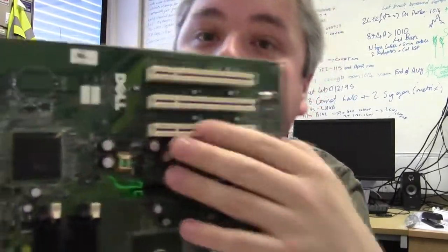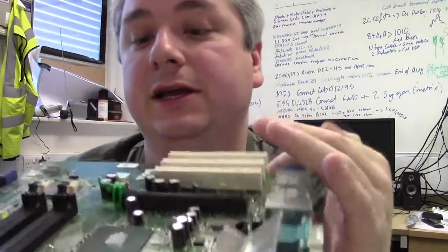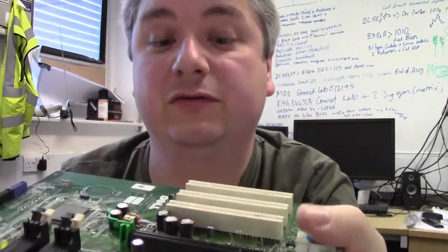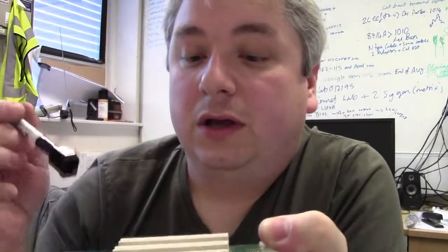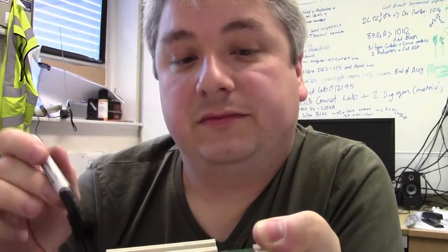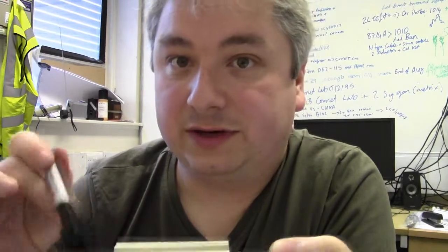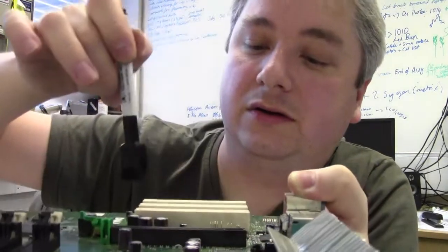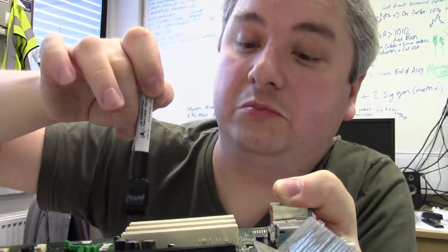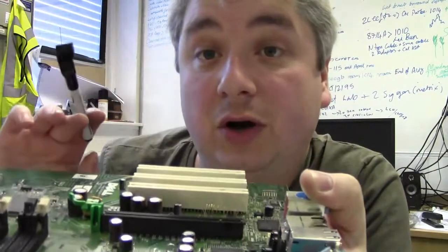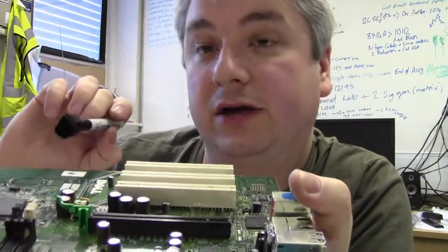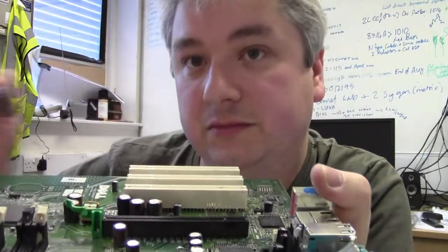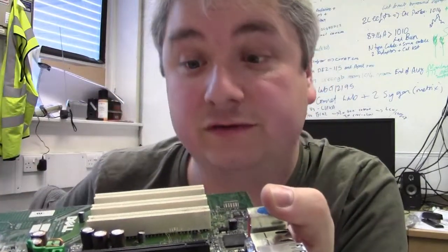Anyway, getting down to these capacitors here, how do you know which one to pick out if you've got to replace it? Well, on caps and on resistors, you've got either your colour coding or your values written directly on. On caps, it will have the values. On these ones around here, 1,500 microfarad is written on, and they've got a voltage rating of 6.3 volts. Perfectly fine. That's what you can go off and go searching for.